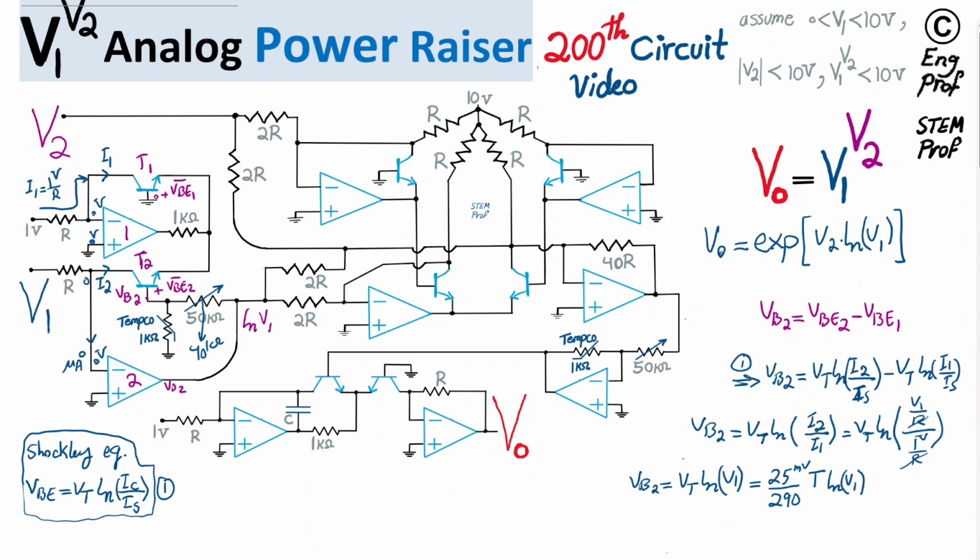Okay, so when that is done, these transistors are low current, so they have a high beta or HFE. The HFE, or beta, or current gain of these transistors, IC over IB, is pretty large, easily much larger than 100, 200. I'm talking about 400, 500. So the base current is negligible compared to the current coming out of the op-amp going through the effective series of 40K and 1K, or the other way, it doesn't matter. That current is much larger than the base current. Therefore, I'm going to neglect the base current of T2, which is on the order of just microamps.